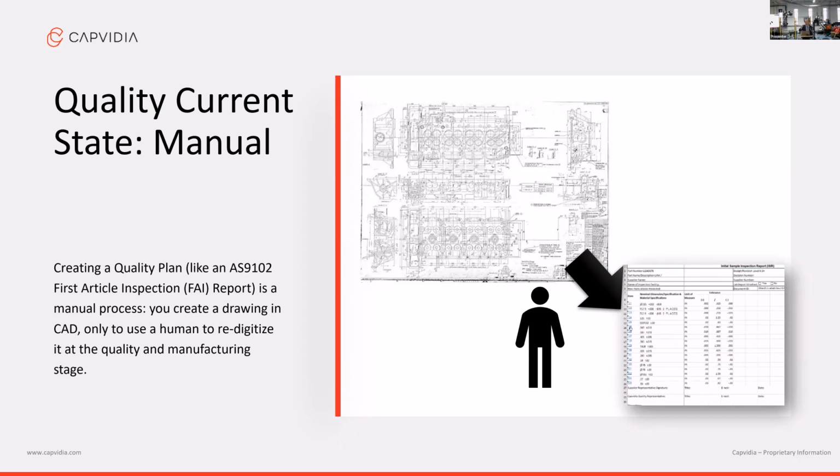You would analyze all of the different annotations on the model that need to be measured. You'd balloon each of them, add little IDs next to each of them, and then you could transcribe each of those tolerances into a table. That's how it's done in the 2D world. And this is a great candidate for an early thing that you could do easily in the 3D MBD world that provides a lot of value and is relatively easy to do.